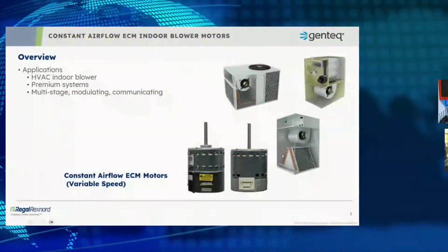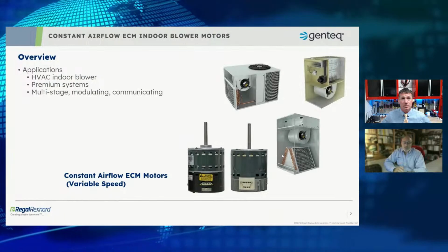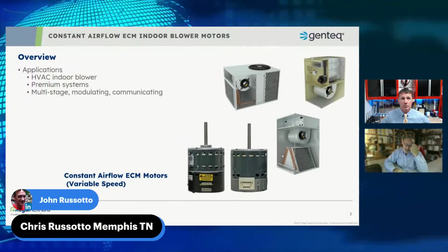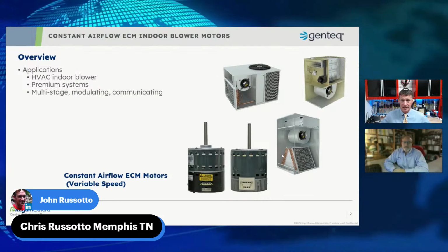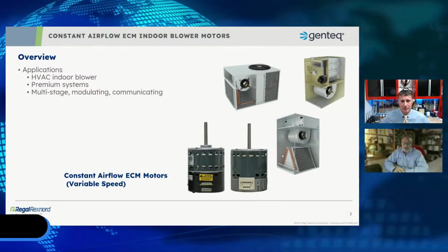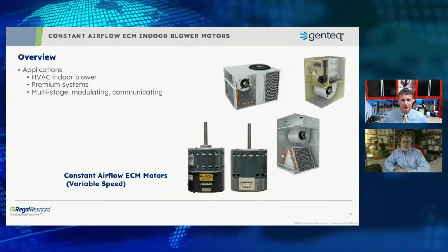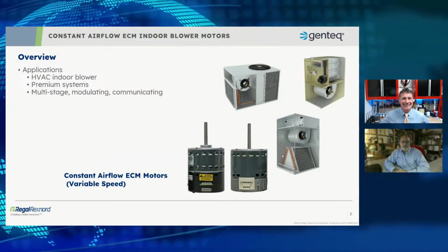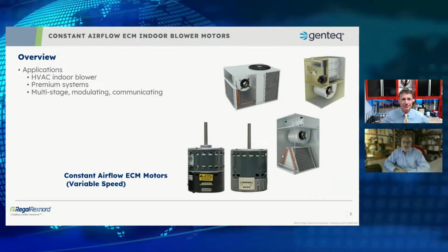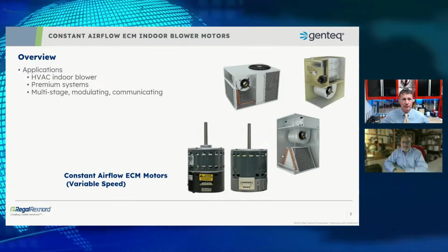All right. So I will jump right into the presentation. Just an overview of, when we say constant airflow motors, the industry knows these motors by the term variable speed. And I don't like the term variable speed, but once you get to know me, I have pet peeves just like everybody else. Variable speed's one of them, because if you take a single speed motor and you change its load point, its speed changes. So every motor is variable speed if you go by that definition.